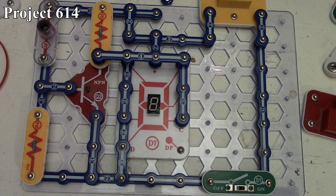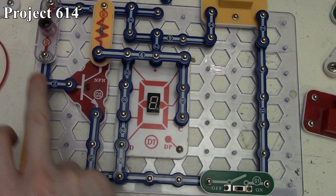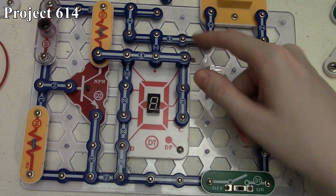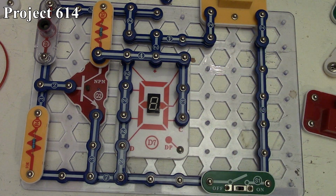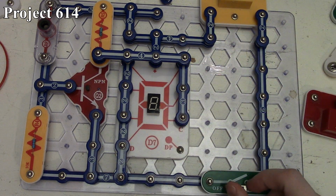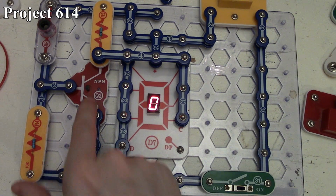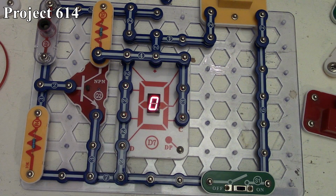And so when we cover up our photoresistor, that will change how much current is getting to the base of our NPN transistor there. Thus it will change how we have some of the segments turned on or off. So when we turn the switch to on, it displays an O because there's light coming into our photoresistor, and that's turning on our NPN transistor.